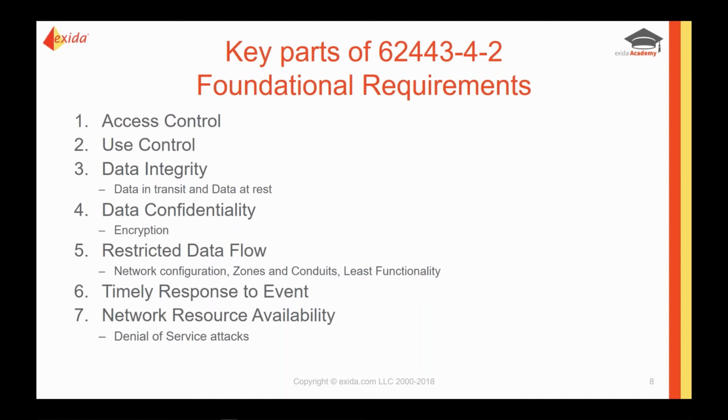There's also the 7th foundational requirement, which deals with resource availability, and this is dealing with things such as denial of service attacks. If you have perhaps a controller and you have determined that there's the potential for a denial of service attack on that controller, you would not want that attack to disrupt the basic control algorithms that are running within the controller. So in terms of designing the architecture of the controller, you'll want to make sure that those things are